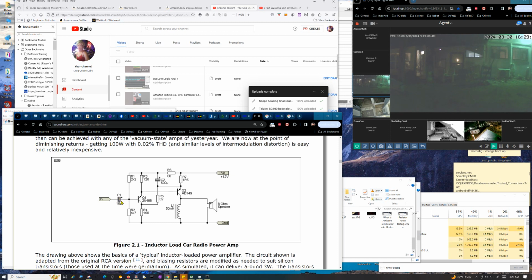which is actually okay. There are occasions you can get away with a capacitor being a short circuit, as long as the current is not unlimited. And if you have a big resistor in series with it, you can actually use it in reverse. It may screw up the capacitor over the long term, I don't know, but the fact of the matter is that it literally will conduct power. So you just want to make sure that power is not so much that the thing gets hot inside and explodes, or is hot enough to damage it, to exceed its temperature rating.